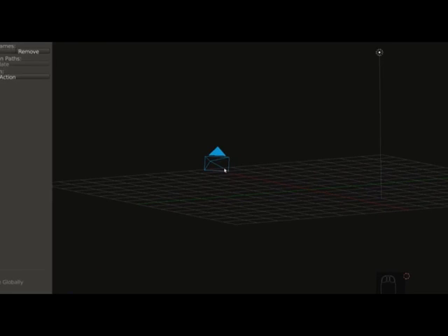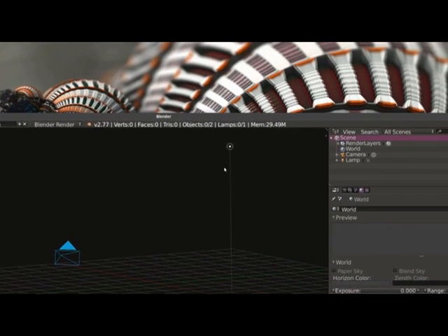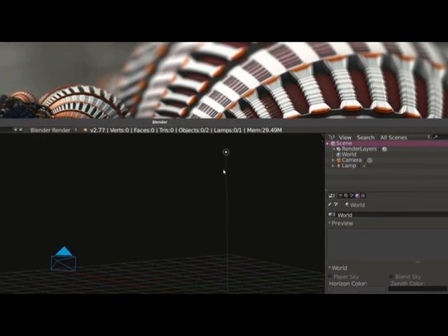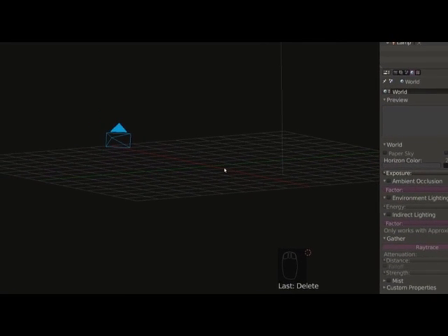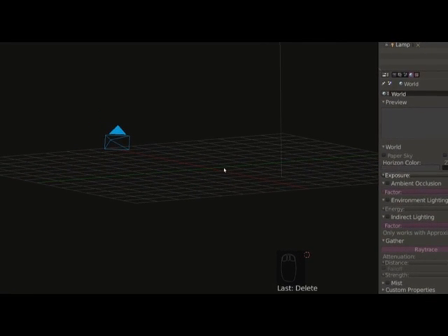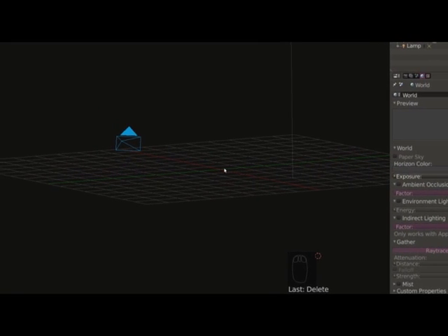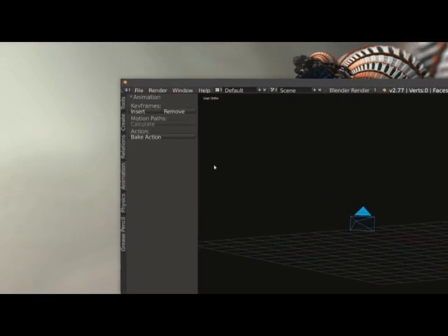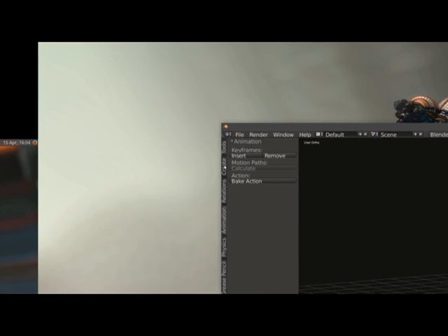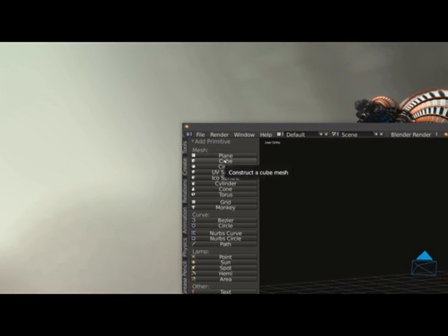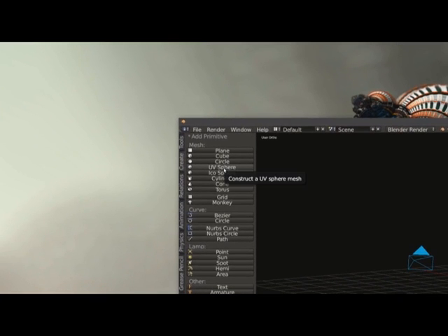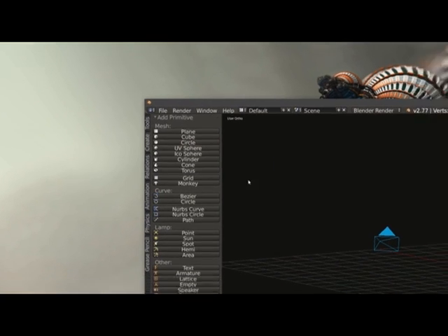Notice this icon is your camera. This is the light source that's in our current scene. This grid doesn't actually appear when you render into a final image, it's simply there for reference. Alright, so the first thing we'd like to do is add a green cylinder and a red sphere. So I'll move over to the menu, tap on Create here on the side, and go to UV Sphere to create a sphere. Click on that.